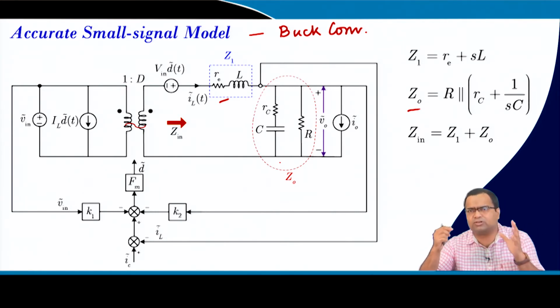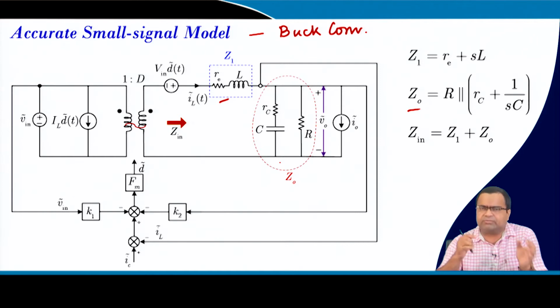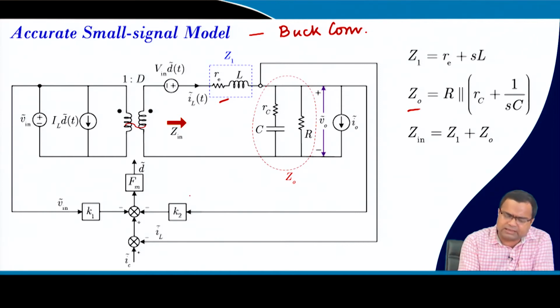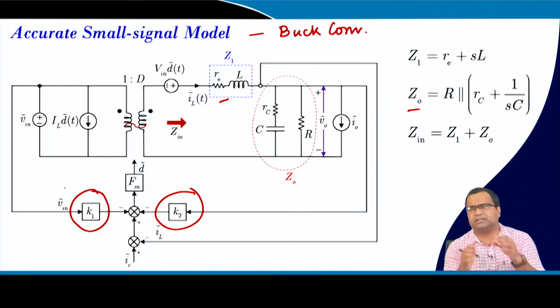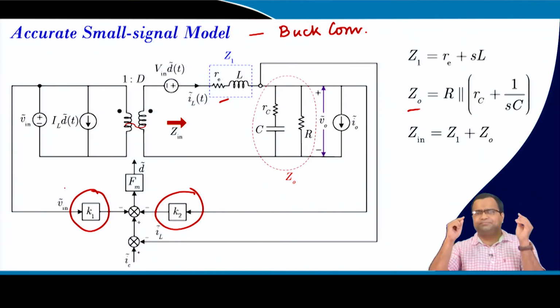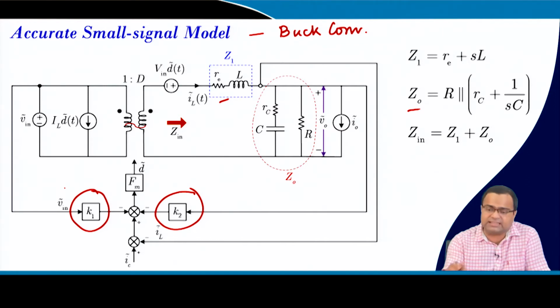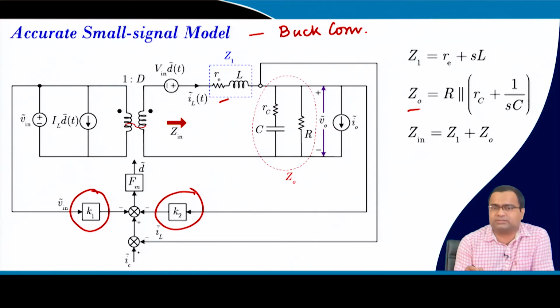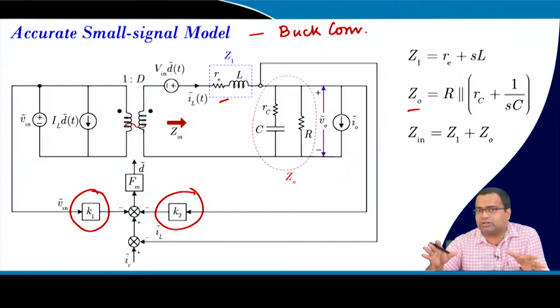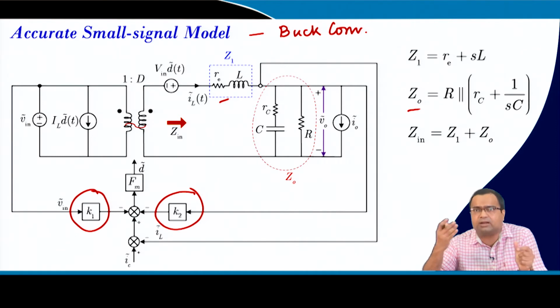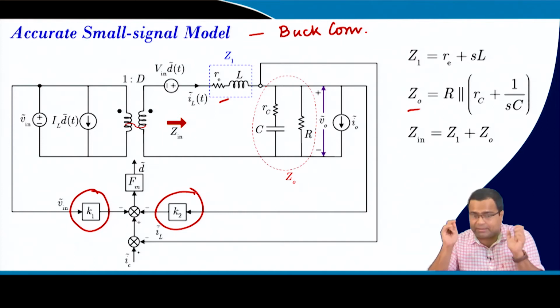Under all these considerations, it is reasonable to ignore the effect due to K1, K2, because the ripple effect is insignificant, and that is why we generally drop it. But in this case, since we are slowing down the current loop, the perturbation in the slope, even in the modulator gain derivation, will be primarily dominated by the compensating ramp.